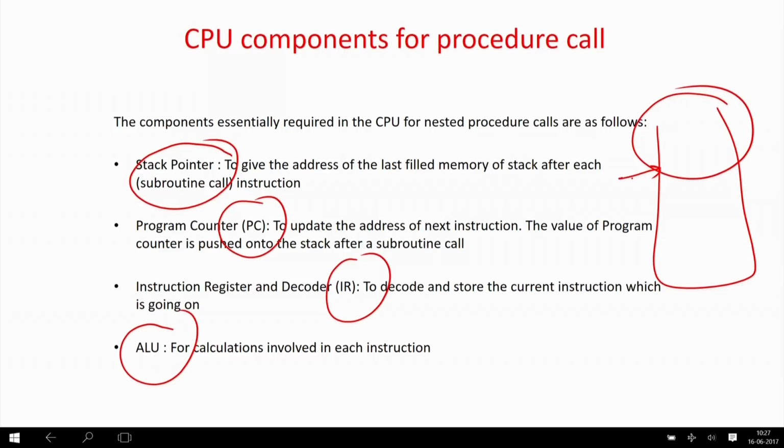There will be a special register which will hold the value of the top of the stack, because after adding some more elements, the top will come over here. So, every time you have to recollect which is the top of the stack. Whenever you want to pop some element from the stack, you will read the register which holds the stack pointer, load the value of the stack pointer to the memory address register, and then you can easily start popping up the values.